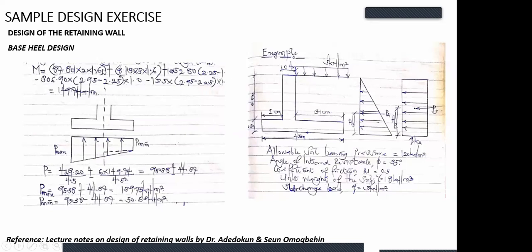So the only thing that basically changed from the moment that we did for bearing capacity is that you are multiplying the horizontal moment by 1.6 each. So let's say that you've generated that one earlier, just rewrite everything and multiply the horizontal moments there by 1.6, then add up again. By the time you add up, you're going to get a new maximum moment, which is 149.7.